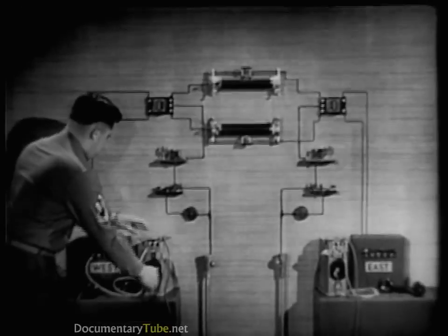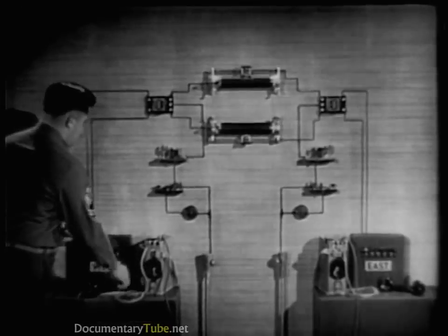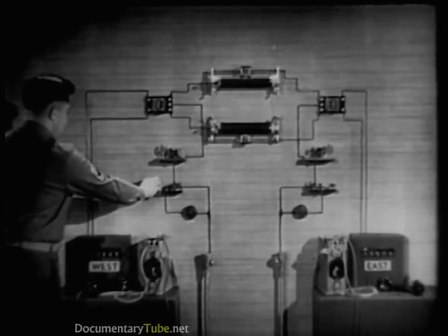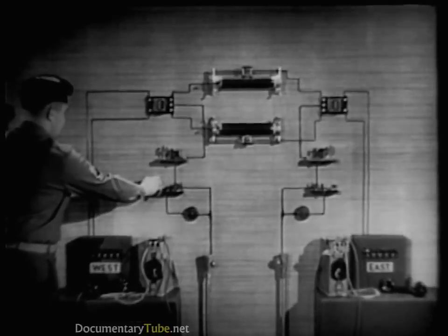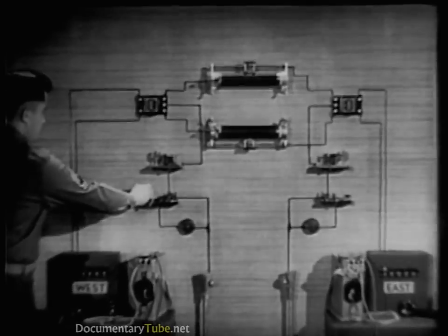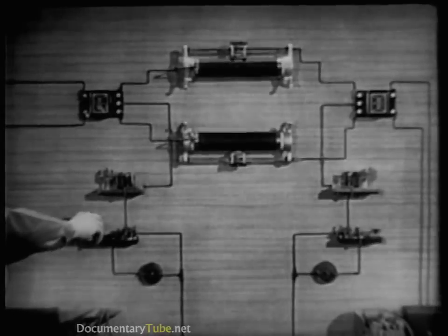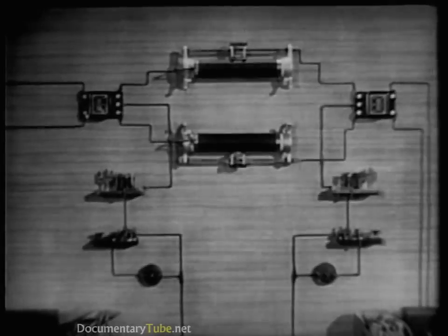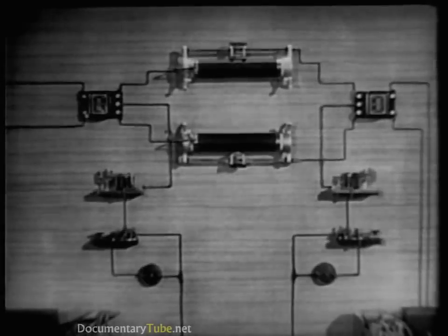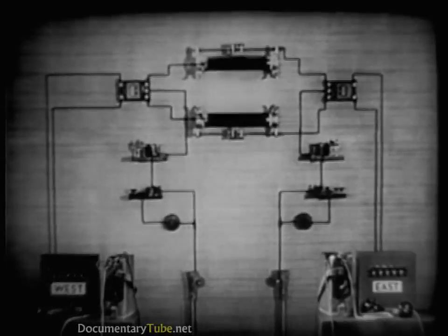The newly installed telegraph circuit can operate without interfering with the original telephone circuit. This new channel is a simplex circuit that may be used for telephone or telegraph. It is rarely used for telephone, however, because like all ground return circuits, it is apt to be noisy.